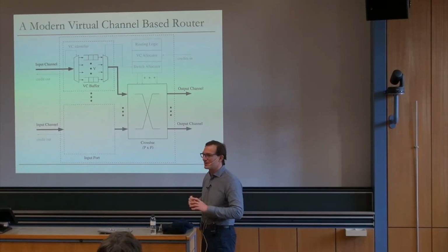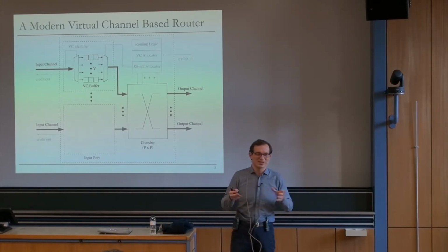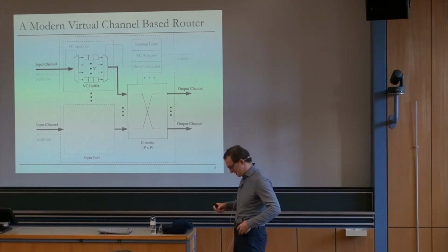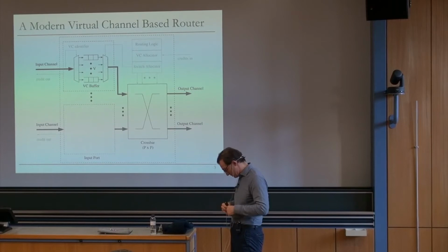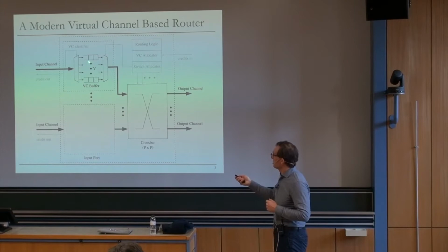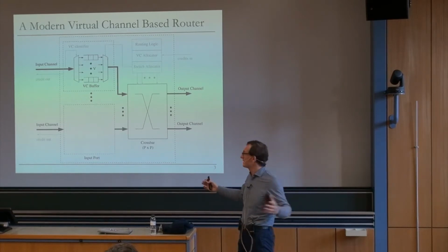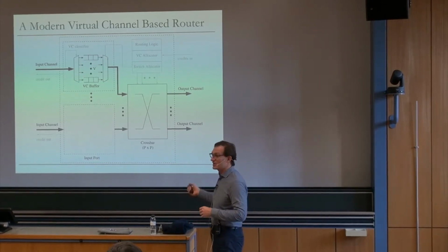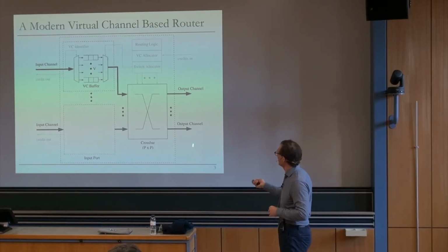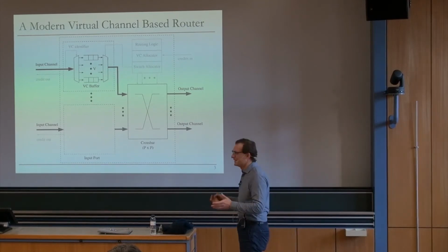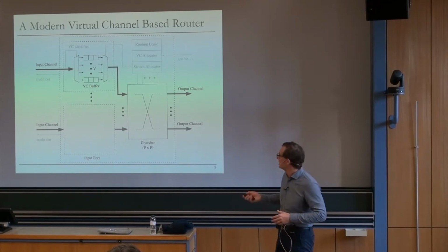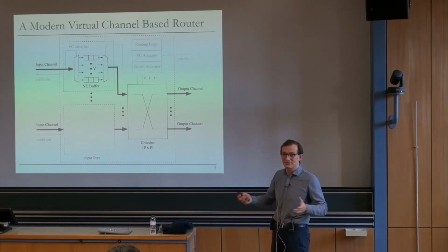So I like thinking about this in comparison to an out-of-order processor. In an out-of-order processor, you have an instruction scheduler also, right? And that instruction scheduler essentially looks at a queue, and it basically tries to pick the instructions that are ready to schedule to some functional unit. Functional units could be output ports over here, right? It's essentially a very similar problem. You just need to make sure the dependencies of the instructions are satisfied whenever you wake them up.